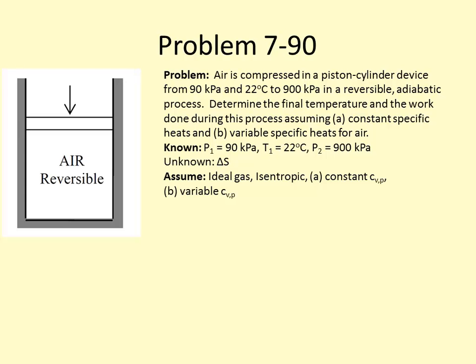So you have to make sure before you just start applying equations to your problems that you know in actuality what assumptions you can make, which ones are applicable in your case, and then start applying the equations. And again, the difference between the exact approach and the approximate approach. If you understand that when you let C sub p vary linearly and you take the average, you're making an approximation. So that's the approximate approach. And then when you're using the tabulated reference values, that's the exact approach.